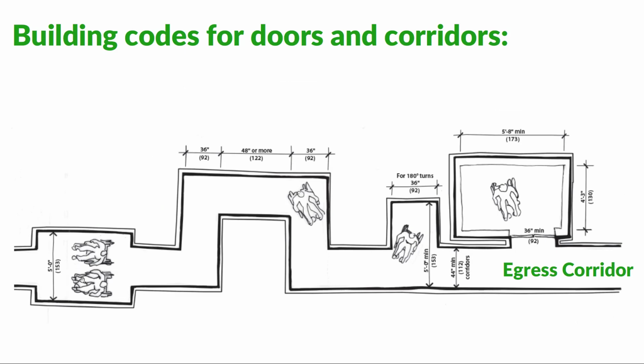Following that same basic path, we see some more really important measurements, including 2 wheelchairs side by side in a corridor. We're looking at a 5-foot width. We have the 36-inch hallway again with that required 48 inches in length we see here. That's so that the wheelchair can turn, get straightened out, and turn again without having to do any kind of difficult maneuvering.